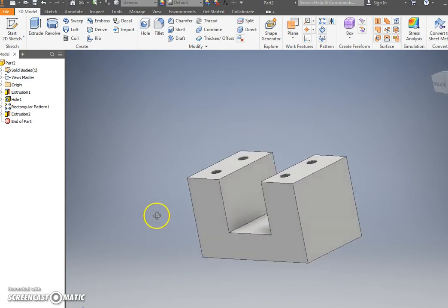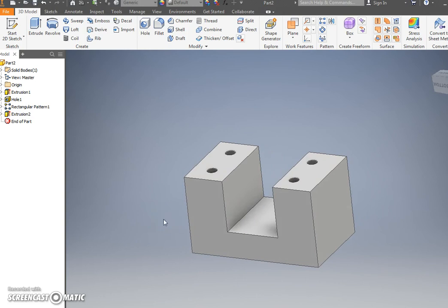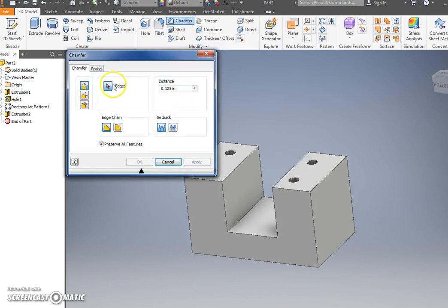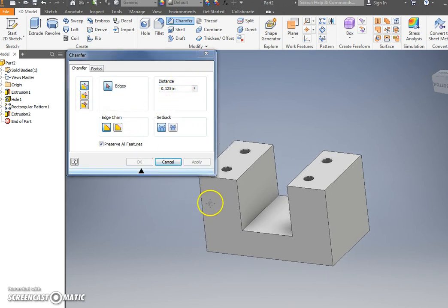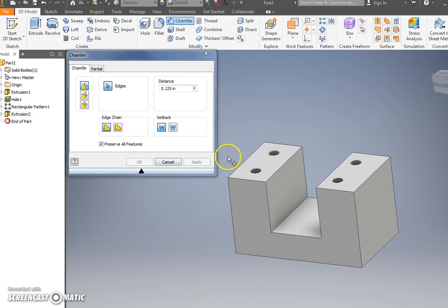We're going to do a chamfer now and a shell, and then we're going to call it a day on this one. So chamfer, up here at the top, you have options. You have distance, you have distance and angle, and then you have two distances. This is where you want 2 different ones. I'm going to do the basic distance. Okay. Click the edges, and it will make a round on there. Okay. So I'm going to do that on the sides and on the back.